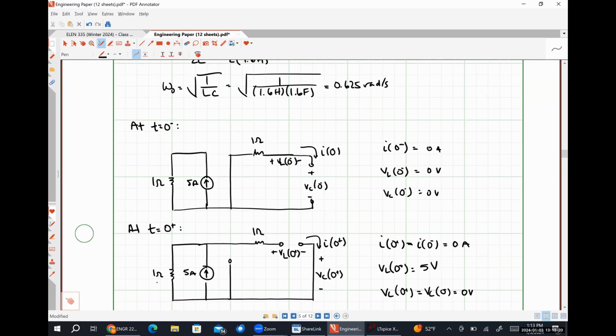So way back here, when we analyzed the circuit at t equals 0 minus, I'm putting in this result and this result as our initial conditions, because our simulation is for everything greater than 0 plus, after our switch changes states. So we have to explicitly specify what the inductor and the capacitor were doing before the switch changed states, so that it knows how to process the originally stored energy, if there was any.